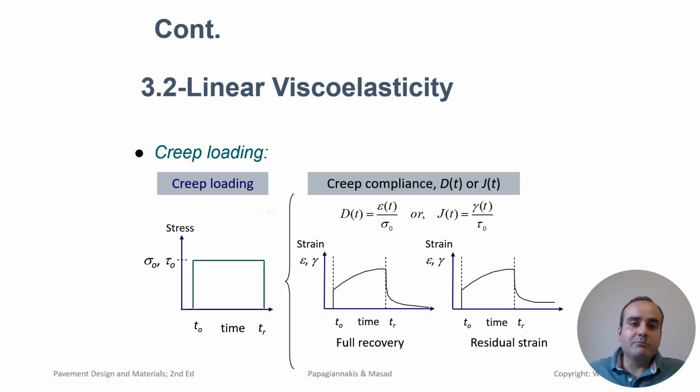In general, the material's viscoelastic nature plays a role in creep behavior. In the viscous phase, the binder flows under stress, leading to permanent deformation, while in the elastic phase, the material attempts to recover after the load is removed. At higher temperatures, asphalt behaves more like a viscous liquid, increasing its susceptibility to creep.